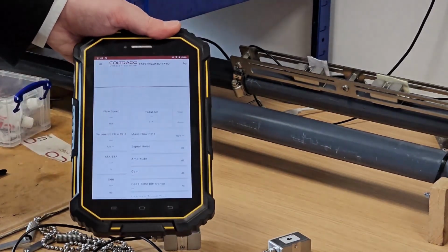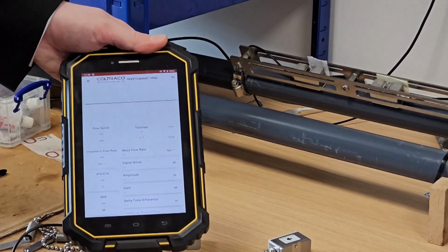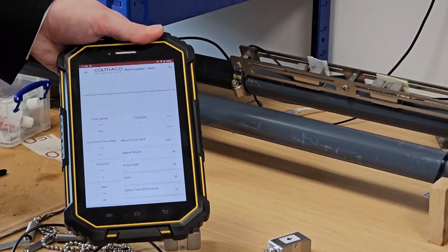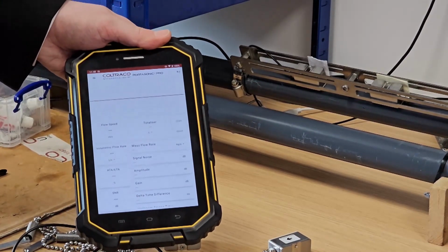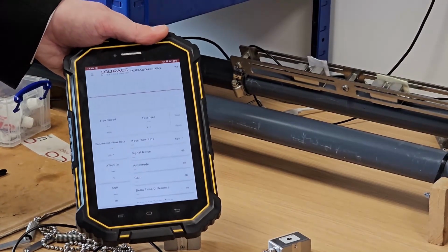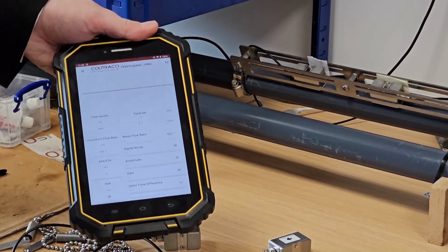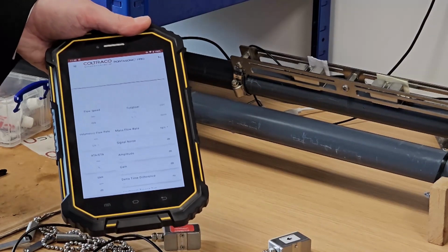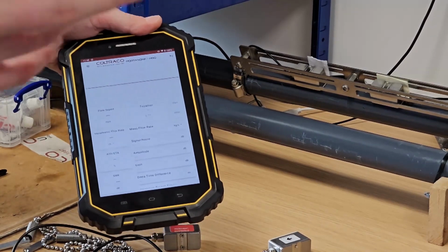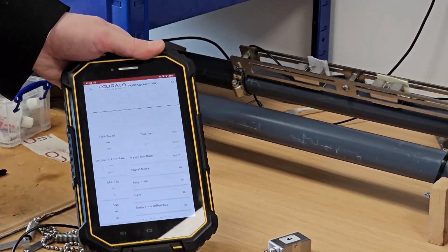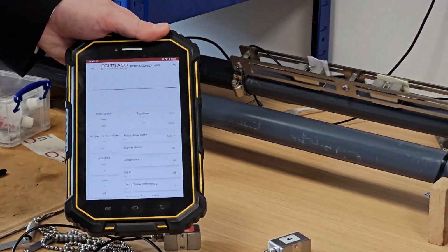You'll see also we now have a totalizer field, which is one of the first new features that I'll talk about, and this simply allows you to measure not only the flow rate in seconds or minutes or hours, but also the total flow that has flowed through your system in a given time frame since you start that totalizer running.